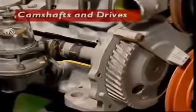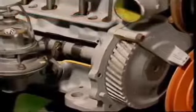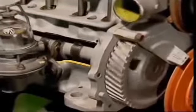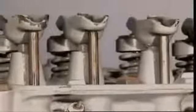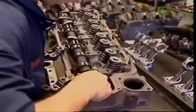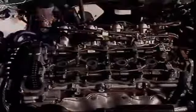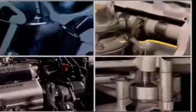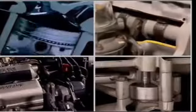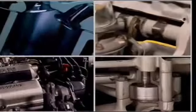This section examines camshafts and drives. The position of the camshaft depends on the design of the engine. It can be in the engine block, close to the crankshaft. This is called a pushrod or overhead valve system. Or there can be one or two camshafts mounted in the cylinder head. But in both designs it does much the same job, driving the valves and the distributor, and sometimes the fuel pump and the oil pump.